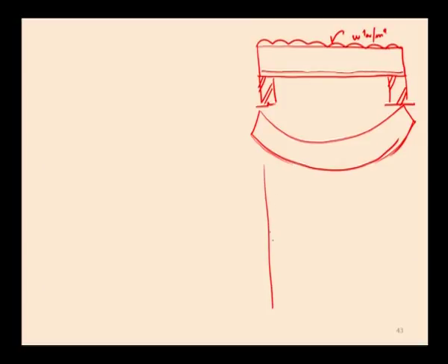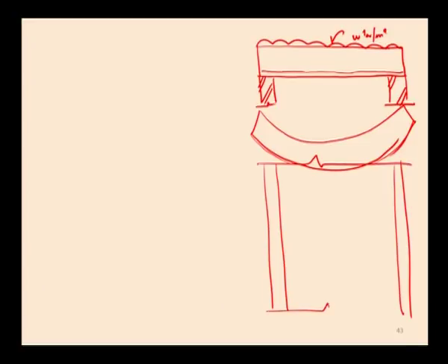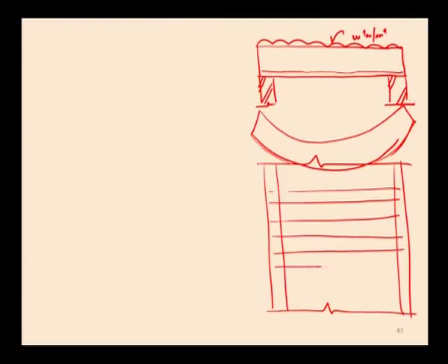So, here this is the plan view, this is the support, you take this as a support and this is the slab portion. The reinforcement normally has to be adopted like this. This is the arrangement of reinforcement in the case of a pure simply supported slab. And this is the bottom reinforcement. After finding the reinforcement, we are going to find the maximum spacing between the reinforcement bars. This is the arrangement of reinforcement. This is called the main reinforcement.